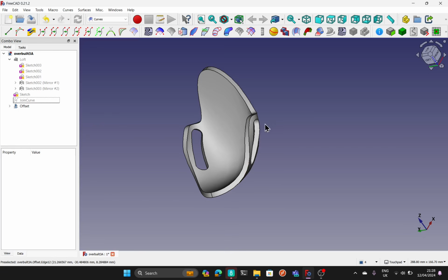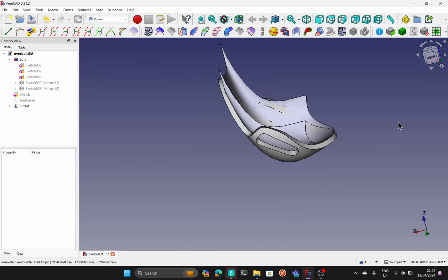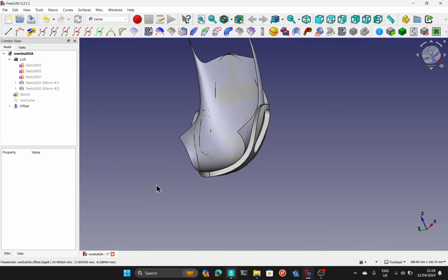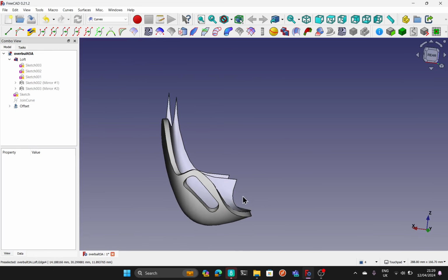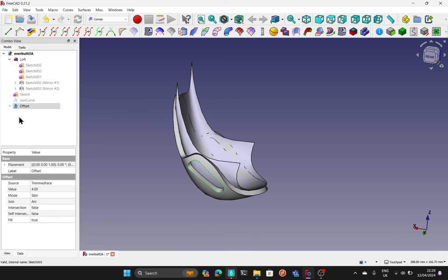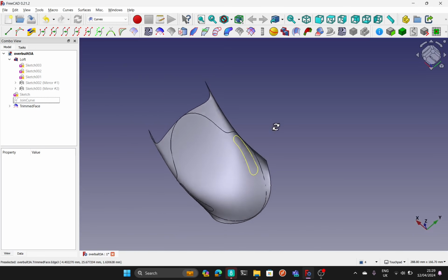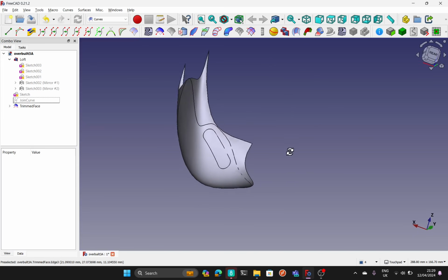We've got cutouts here. And if I bring back the overbuilt surface, the loft, you can see what's happened. So we've used a surface that's larger than the object itself. A simplified surface that we can use to trim away from. So we've trimmed away this here and this shape here from that surface. I'm just going to delete the offset. And now we get to the point of seeing what the surface looks like. So we've got two surfaces now, the overbuilt one and the trimmed one.